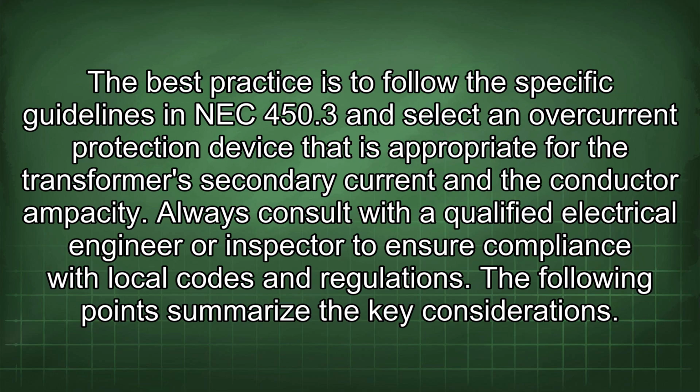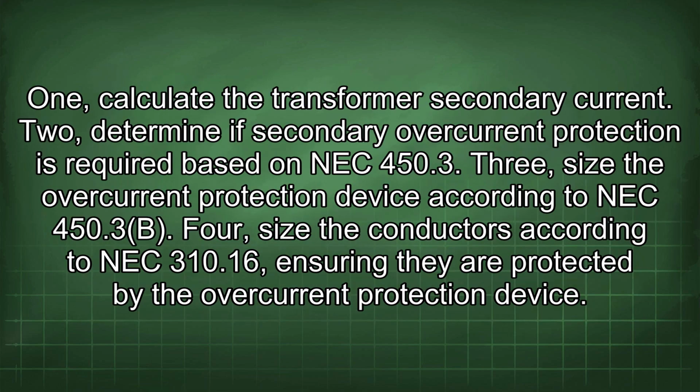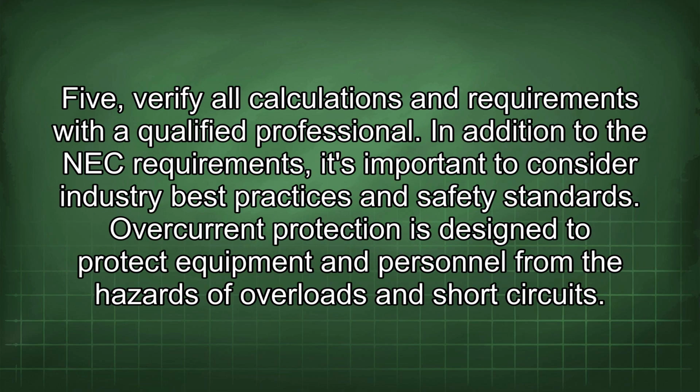The following points summarize the key considerations. 1. Calculate the transformer secondary current. 2. Determine if secondary overcurrent protection is required based on NEC 450.3. 3. Size the overcurrent protection device according to NEC 450.3(B). 4. Size the conductors according to NEC 310.16, ensuring they are protected by the overcurrent protection device. 5. Verify all calculations and requirements with a qualified professional.